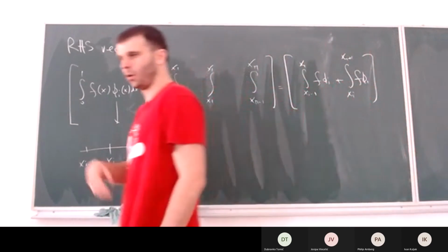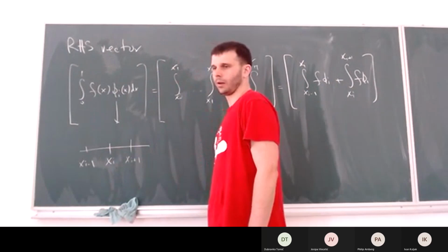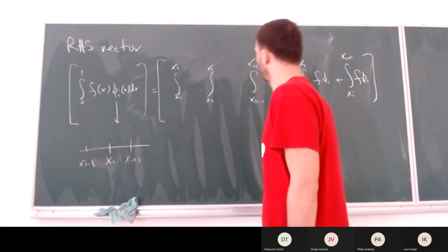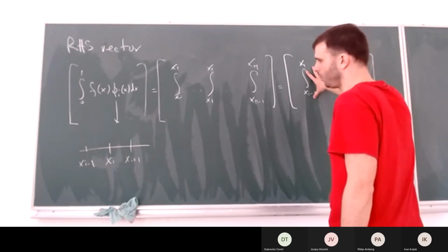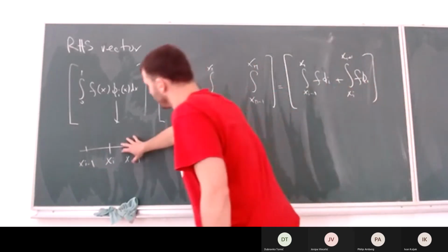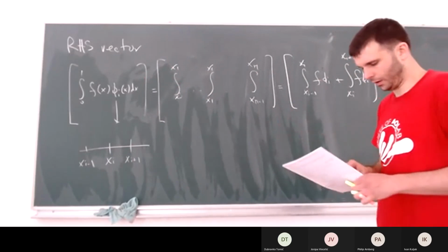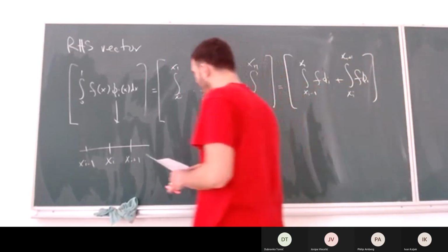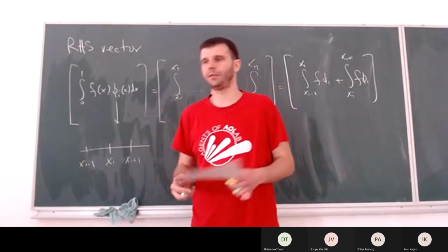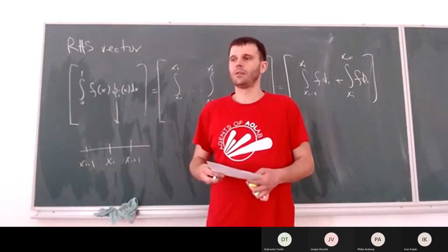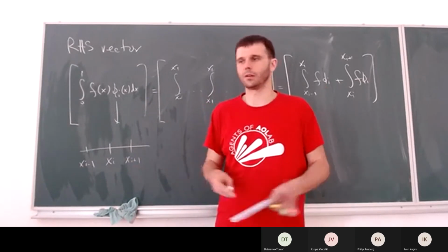So while we are looping through the elements constructing the local stiffness matrix, we will also construct a local load vector. On this element, we calculate the integration on this portion. Going to the other, we integrate on the second one and put it in the global positions. Okay, so now we basically know how to construct the stiffness matrix and the right-hand side. We just have to plug in P1 elements to see what the matrix looks like.